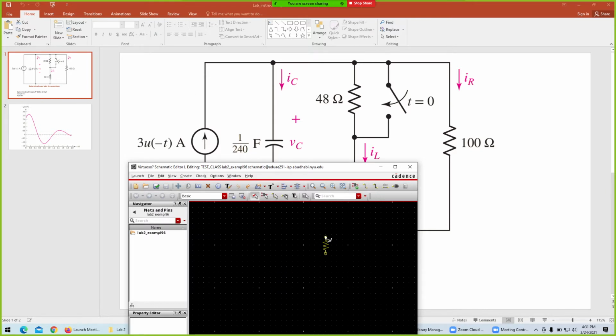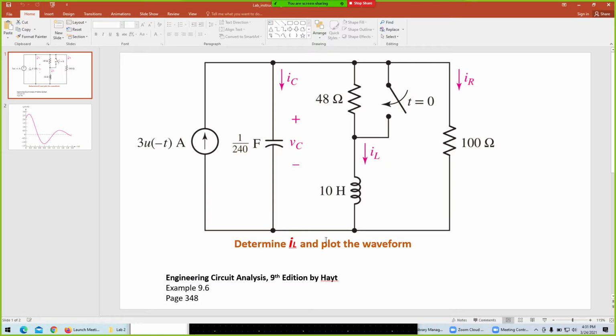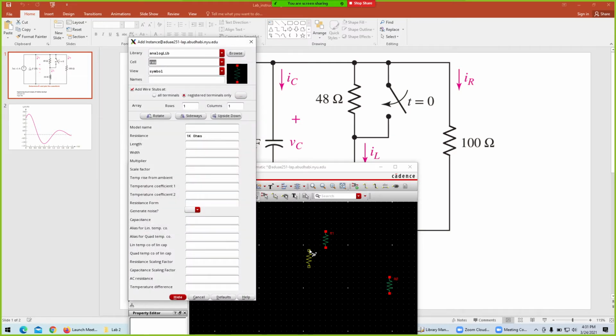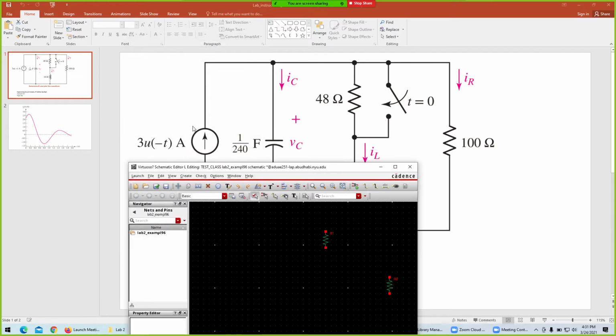So I have one resistor at the output, another resistor over here. What else do I have? We have two resistors, one inductor, one capacitor. So I'll instantiate, and your cell is already highlighted here, so you don't have to bring your mouse in, just type cap for the capacitor, enter, enter.